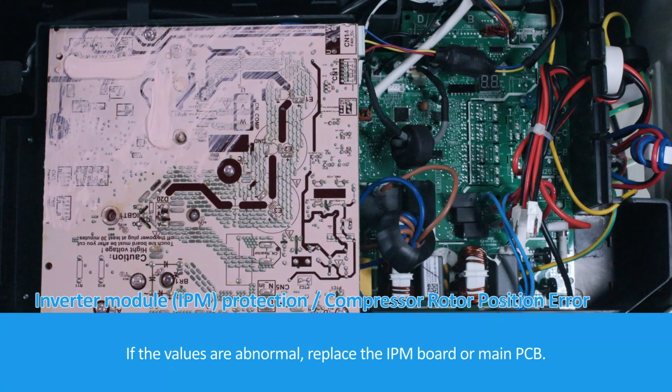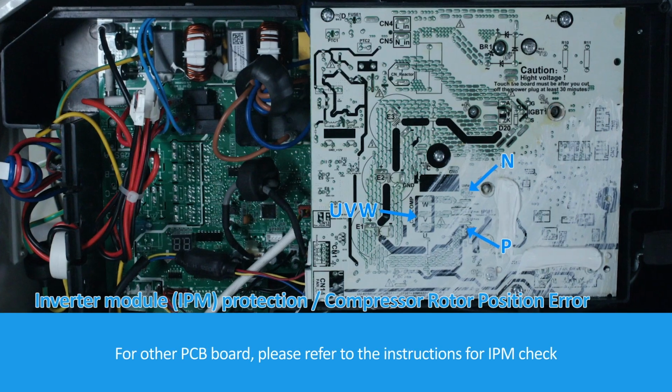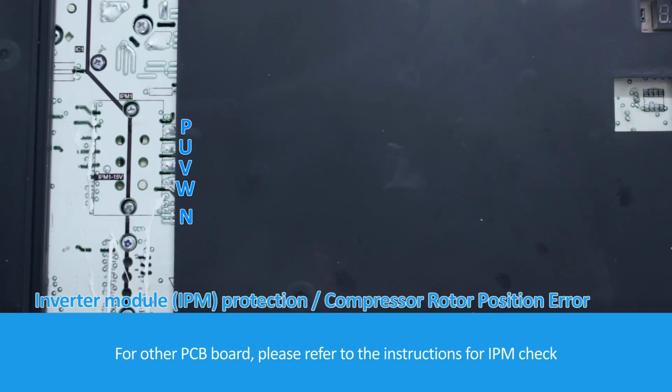If the values are abnormal, replace the IPM board or main PCB. For other PCB boards, please refer to the instructions for IPM check.